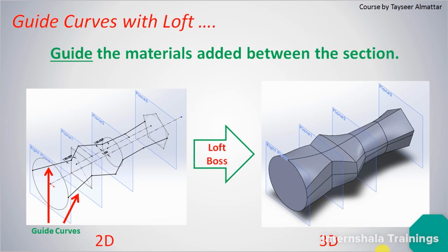We can further restrain and guide our Loft Boss using what's called guide curves. If we apply the shown guide curves on the left, we get the object on the right, which looks very different than the shape we got in the previous slide.